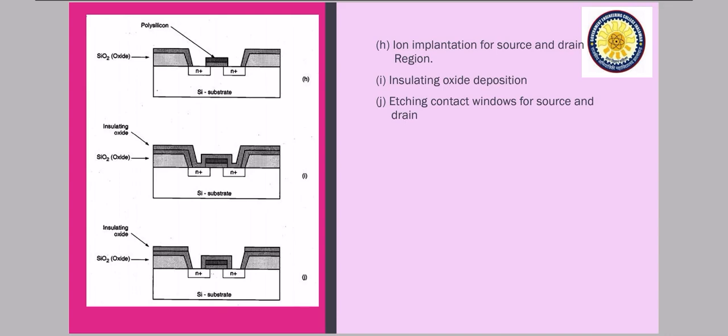So you can see in the previous step that the doping penetrates the exposed areas on the silicon surface, so it can ultimately create your source and drain regions. And this process means wherever we want to grow your source and drain region, it will come below your polysilicon layer, which basically makes your channel part.